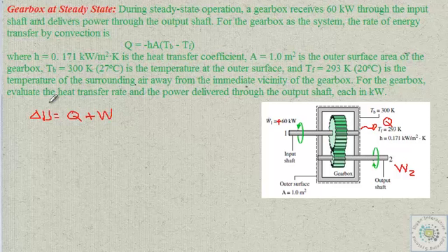But if we take a look at this on a flowing basis, we'll differentiate this with respect to time. We'll have delta U over dt, delta Q over dt, and delta W over dt. In this case, this will then become Q dot, meaning how much heat is added or removed from your system, and work over the change in time will just be W dot, meaning rate of work per unit time, and this one dU dt.